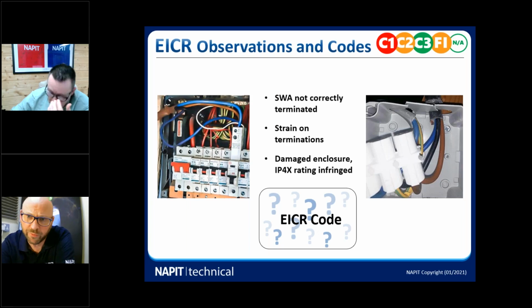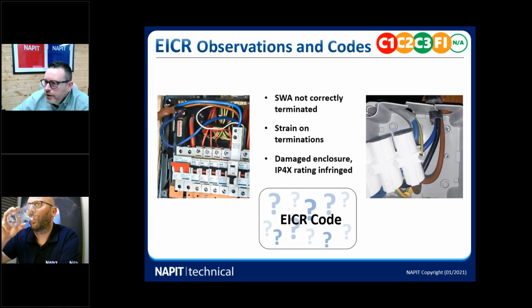Frank, you got any comments on induced voltages? There's still some comments, connected to earth to stop those circulating currents that can be induced in those conductors. Again, it could be voltage in there. You can cause some problems in some cases when it goes through. So it's always recommended advice for unused cores to either be terminated to earth and labelled up as that and marked so it is identified of what they actually are.